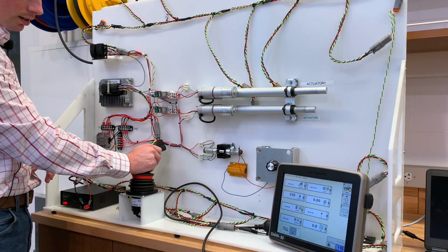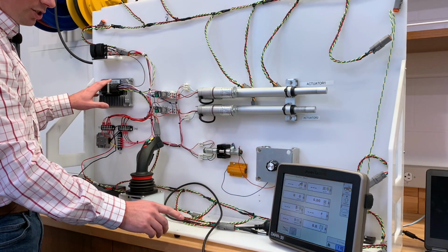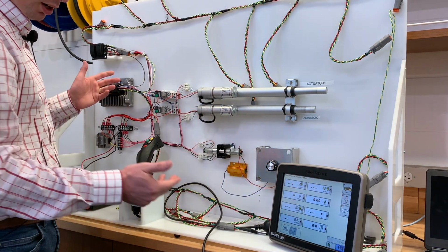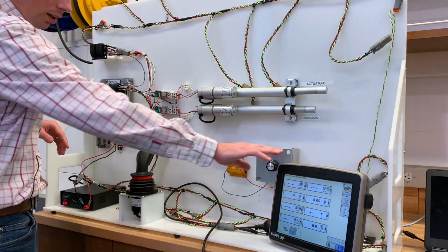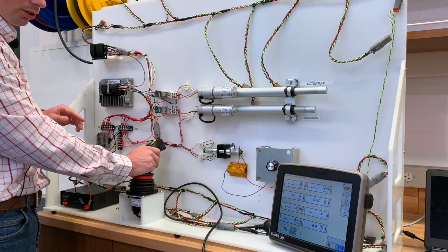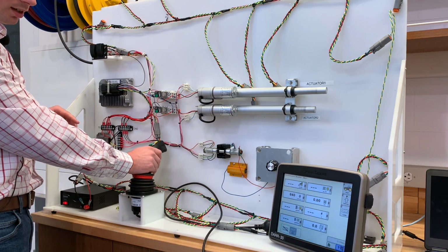the actual motor speed. One thing you'll notice is we're outputting a J1939 CAN message that is engine speed, so we're emulating that we're an engine, and this shows up on the display page on the ISOBUS display. As I push this joystick forward, you'll notice the engine speed shows up and increases. We can load that up.